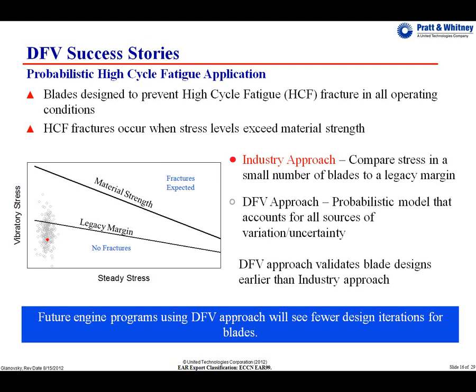They'll plot out their material strength for the material the blades are made out of. And then they'll take a small number of blades and actually test them against varying levels of strength. At the end, they'll record the highest level of stress seen on any one of those blades, just the maximum.